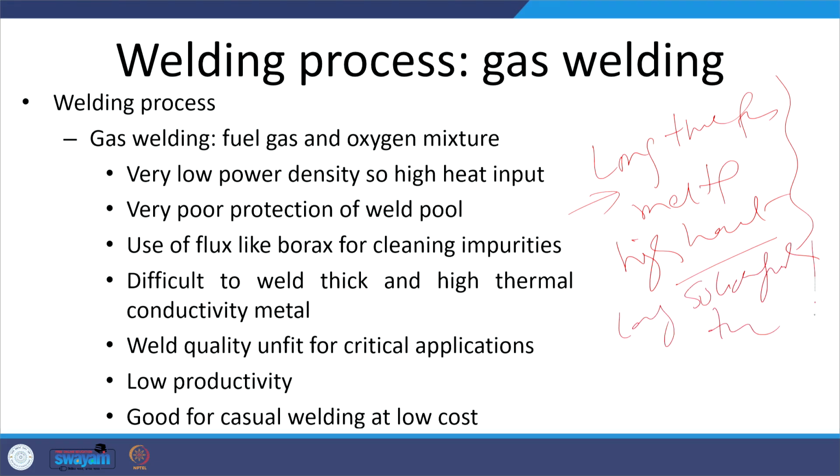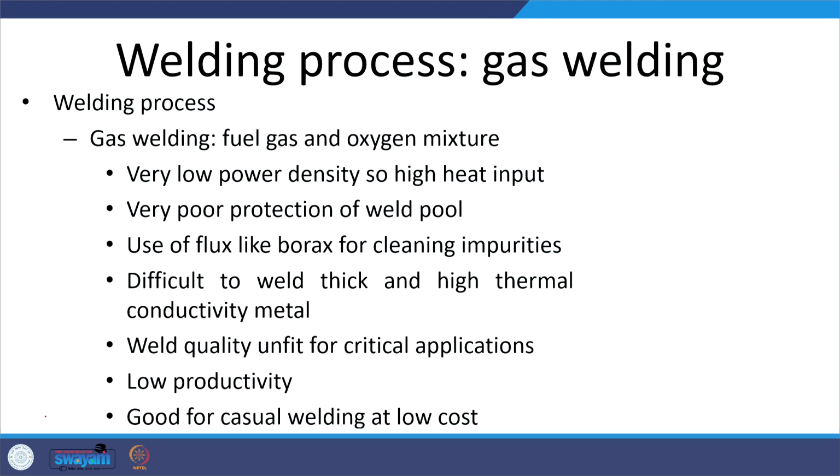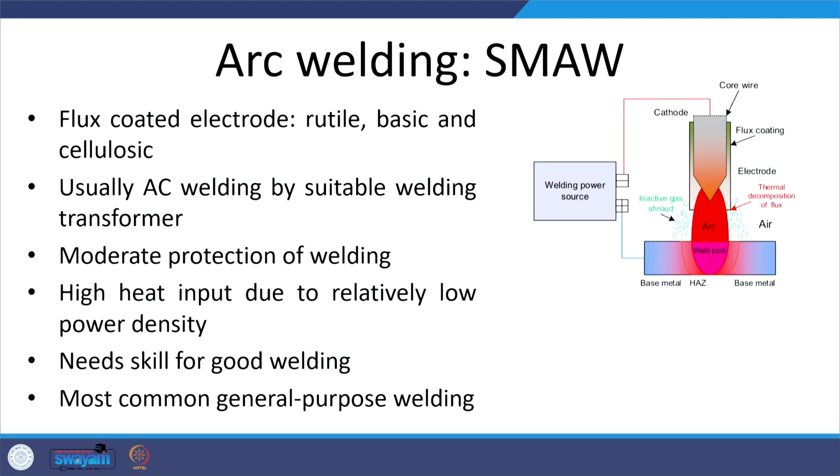So these things make the welding a little slow, and that is why the productivity associated with gas welding is low. But since there is no major infrastructure of machines and systems required for gas welding, it is a low cost approach and primarily used for casual welding applications, but not for critical applications.